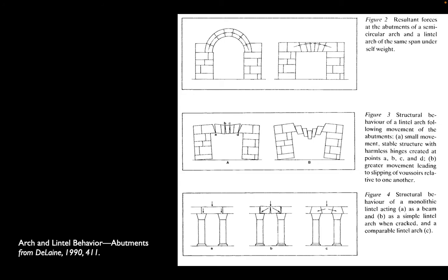If you think about it, if you push down on an arch, it's going to try to push its buttresses, or its buttressing walls, out, right? That's the way it's going to want to fail. The Romans realized this. They were very good at sizing their supporting walls to be adequate to both the vertical load, but also to the horizontal thrust that's implied by an arch.